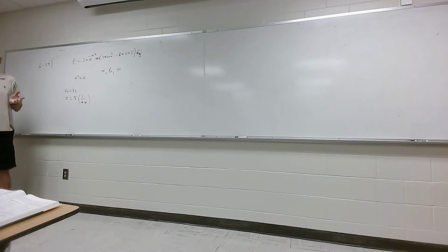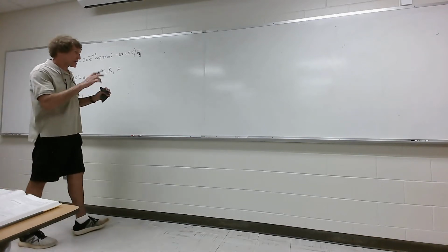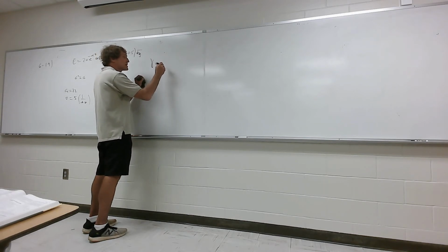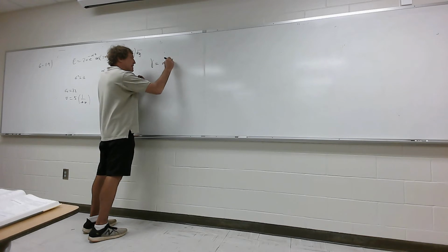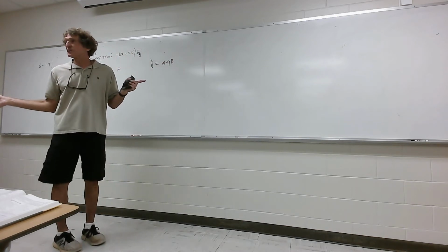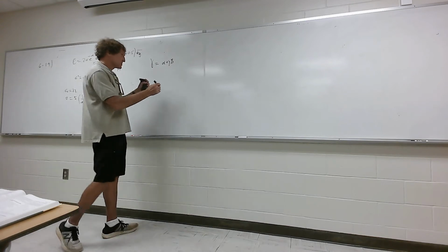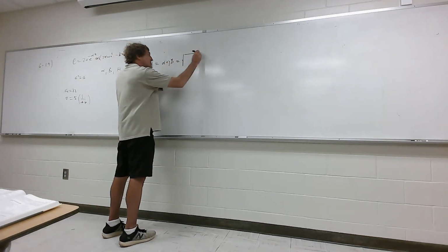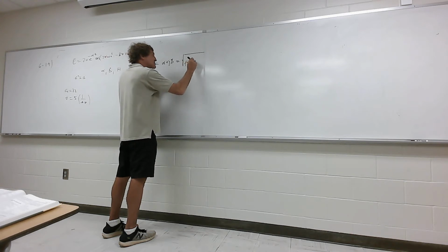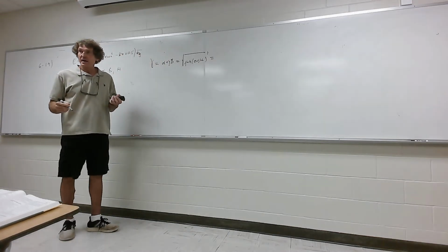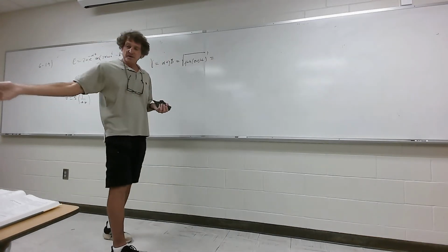So, how do we do this problem? Well, first, think of the fundamentals. Anytime you have any kind of problem at constant frequency, the propagation constant is alpha plus j beta. Now, we don't know if it's a good conductor or a lossy dielectric at that frequency. They're asking us to find it, so just do the whole nine yards. That's the square root of j omega mu times sigma plus j omega epsilon. Y'all agree with that, class? Now I'll put the values in, and you punch them out in your calculator and give me the answer.